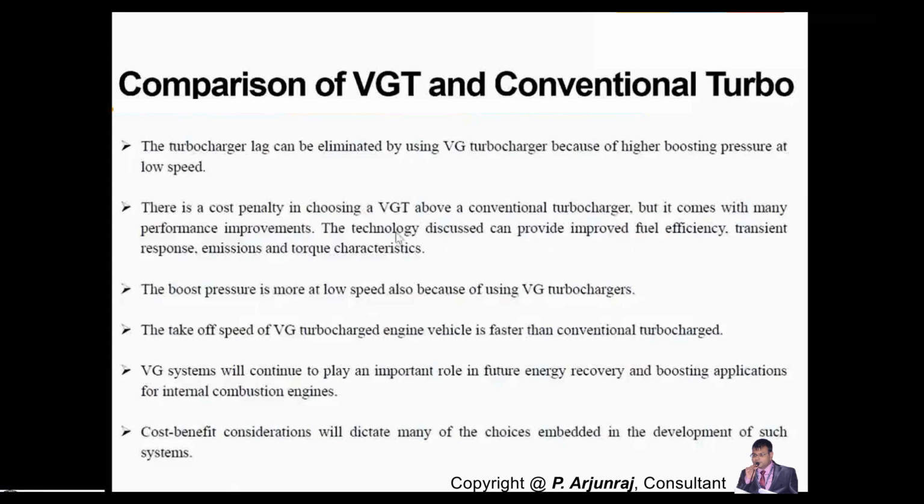Okay, and it will also help you to increase the transient response, emissions, and torque ability. So you have a lot of advantages. And see, when you're going for a variable geometry, that will help you to increase the pressure. I told you it's nothing but the boost pressure. When you increase the boost pressure, all the advantages are there. Basically, this is good for a low speed application.